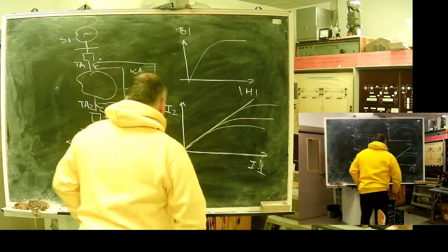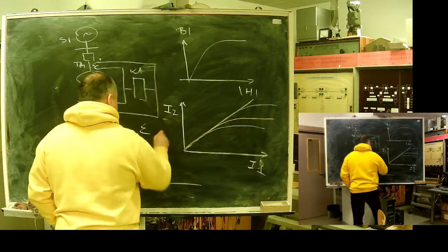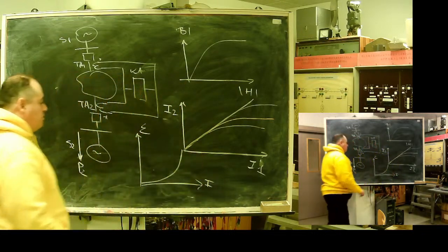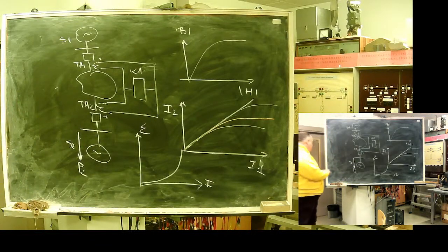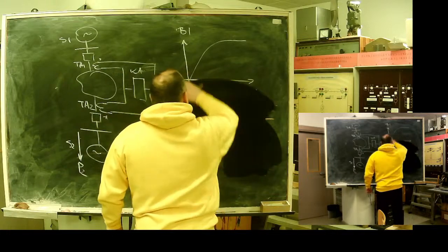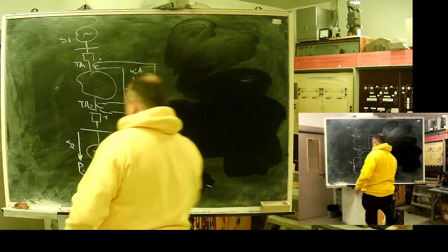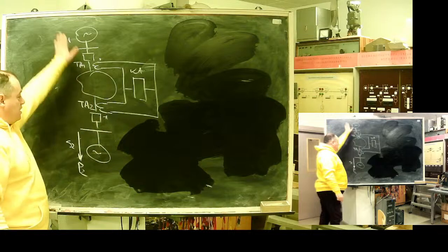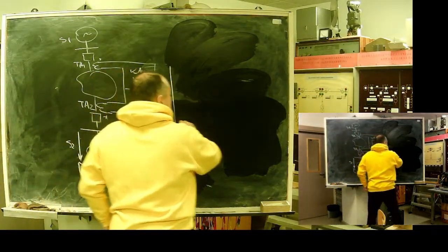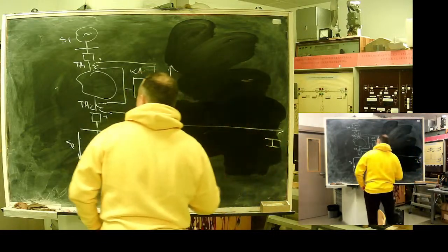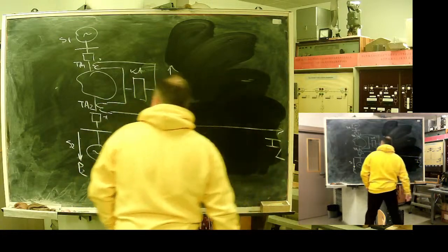So, the error of the transformer, we will see something like this, a group of error curves. In our case, the error itself is not a giant problem. The problem is what we have outside load, outside fault, current going through. Let's say if there is load, current goes through.